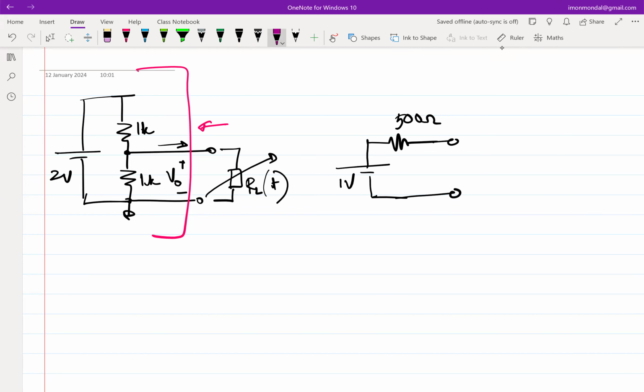This becomes the box, and you have RL here. And then we further said that, let's say this RL varies between 100 ohm to, let's say, 1 mega ohm. Then all of you rightly pointed out that the issue will be with this 100 ohm, simply because if you have 100 ohm, you have a lot of current which will drop across the 500 ohm resistor, right? And our output across RL will fluctuate meaningfully from 1 volt, right? So this is where we were.